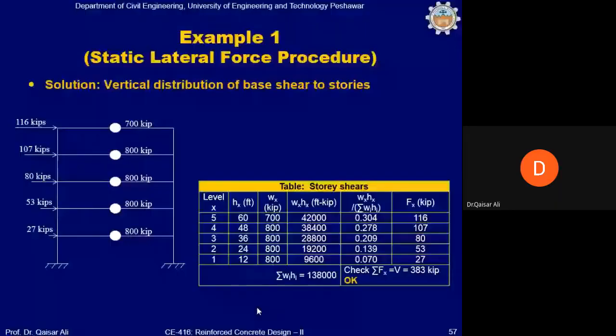Okay, so we'll move ahead with the structure in this manner. And now you can analyze the structure along with the gravity load. If these forces are applied, this will produce some stresses, bending moments, and these bending moments can then be added to the gravity bending moments.